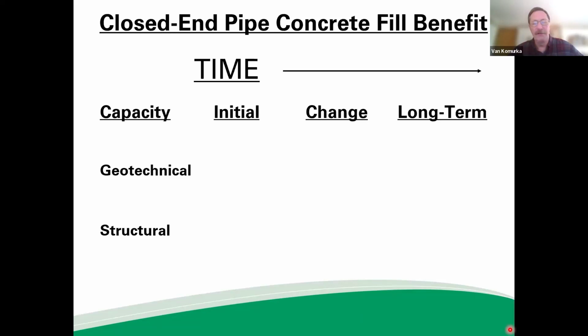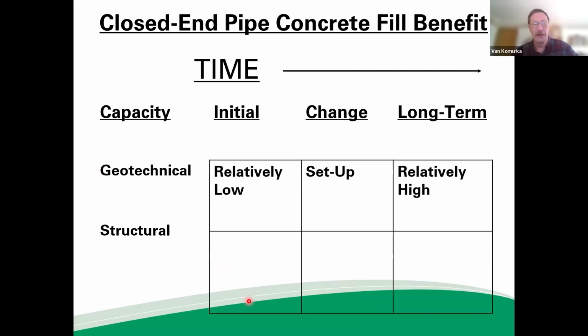Let me say that again. After driving, you can change the structural capacity of a concrete filled pipe pile, and it's the only pile type with which that's capable. So if we look at what's going on here, and this is mostly in terms of economics, remember, you design piles for two capacities, both structural and geotechnical. But often the structural is overlooked when a geotechnical engineer is putting together a program.